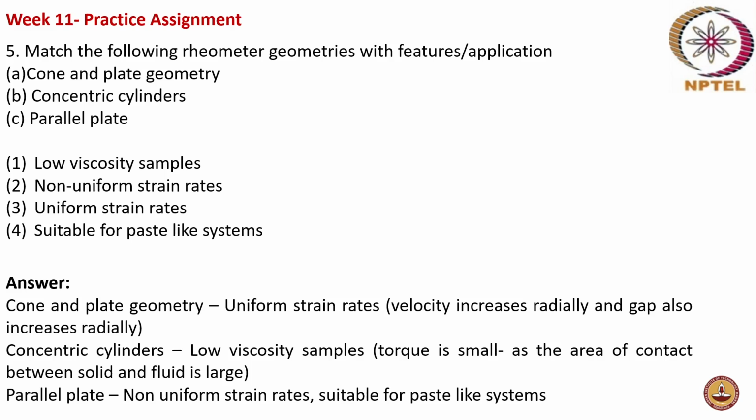For example, in case of cone and plate geometry, we have very small gaps of 50 micron between the cone and the plate. Whereas when it comes to parallel plate geometry, you cannot use that small gaps for a particulate system. Okay, paste-like systems and all, we have considerable sized particles. But in case of parallel plate geometry, the gap can be some 500 microns to 1 millimeter. So this can be used for particulate systems.